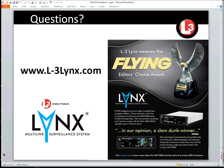And then there's some Canadian operators who purchased Lynx and wanted the diversity option right off the bat because eventually they're hoping that the Canadian government is going to provide them with a similar free weather information via a satellite-based system, and a diversity device would be able to receive it from a top-mounted antenna as well. But I typically tell people if you're not going to be flying a large aircraft, Beech 1900 or larger really, you really shouldn't need diversity for any reason.